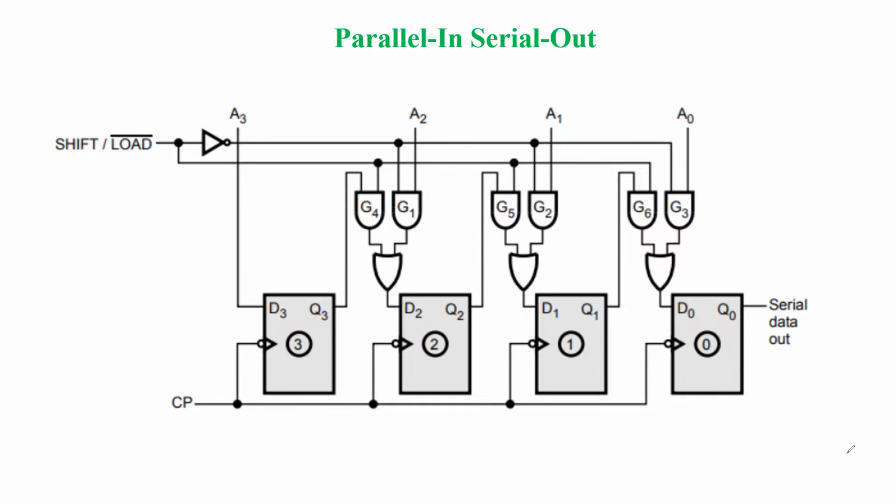Hello, in this lecture, I am going to discuss one type of shift register that is called parallel in serial out. Here, on the top, the data is given as the input, that we have here as parallel in. Now, we have taken four flip-flops here, and we are taking the D flip-flop.